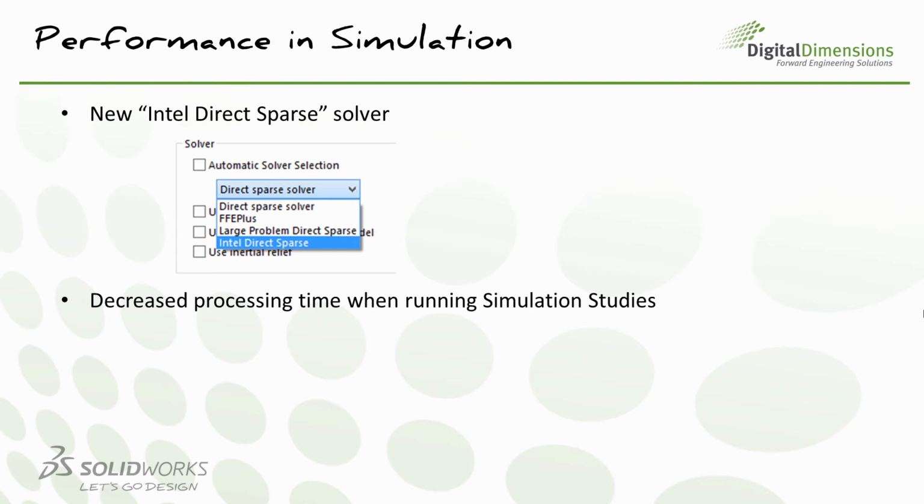Now, in the area of performance, there are a couple of items that are worth mentioning. The first one is a new solver type in simulation. The new solver type is called the Intel Direct Sparse Solver, and it's available for static, thermal, frequency, linear dynamic, and nonlinear studies. Now, the idea behind this new solver type is that it's more efficient at memory allocation algorithms and using the multi-core processing capabilities of our Intel chipsets when solving calculations. So if you have an Intel CPU, you may want to try running the Intel Direct Sparse Solver.